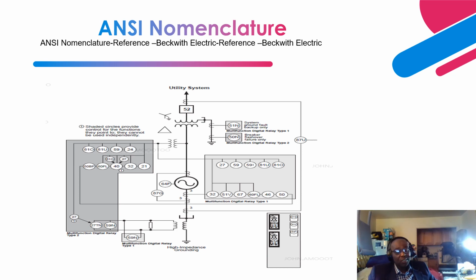Next is loss of excitation, and this is an impedance-based protective relay measurement, and it's based on the setup of the magnetic field on the rotor, right? If there is a fault on the rotor, or a fault somewhere in the stator, this relay detects the change in the magnetic field based on changing impedance, and it's able to trip the required breaker.